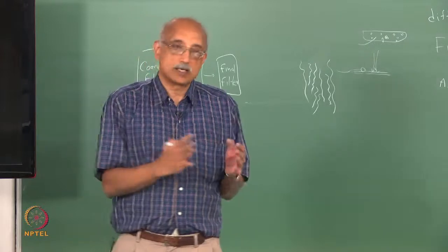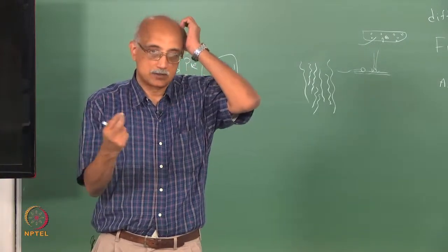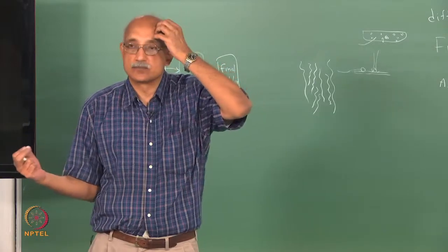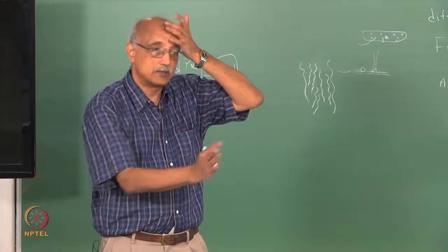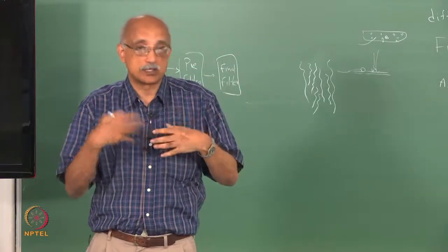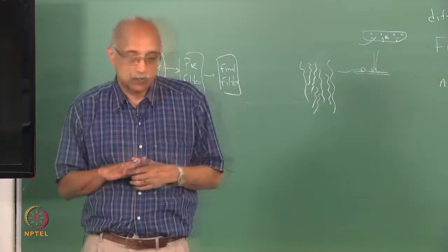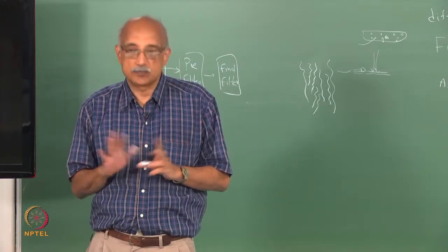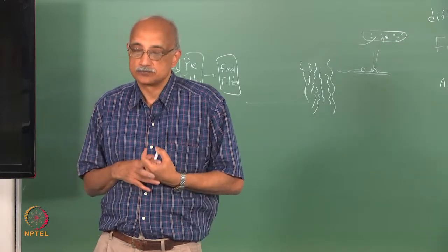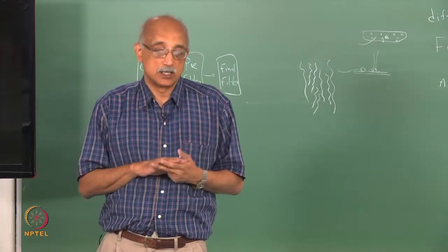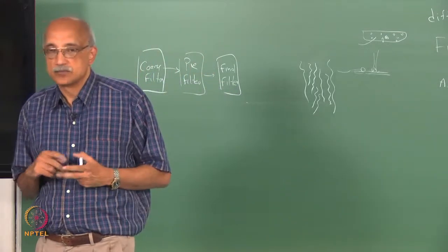So, as you do that, what you will form is a thin sheet that has porosities in it. So, that is the way fibrous filters are manufactured. They are made in sheet form, they are stacked as rolls, they are sold as rolls, and they will have a void fraction of about 10%, a porosity of about 10% as manufactured. So, in this process, as you can imagine, cleanliness is not a major criterion, right.